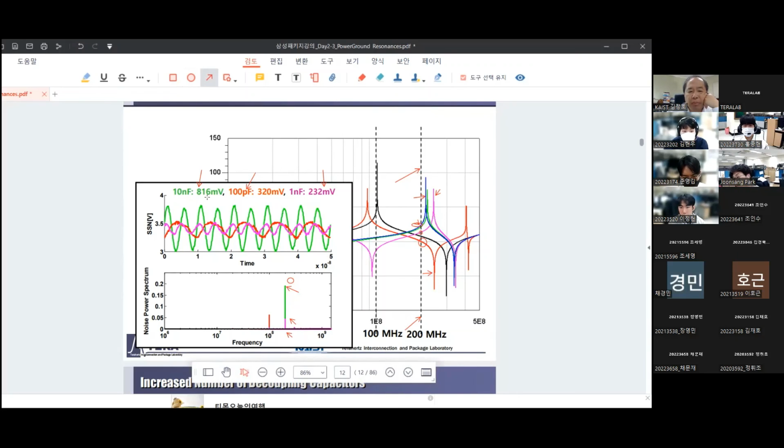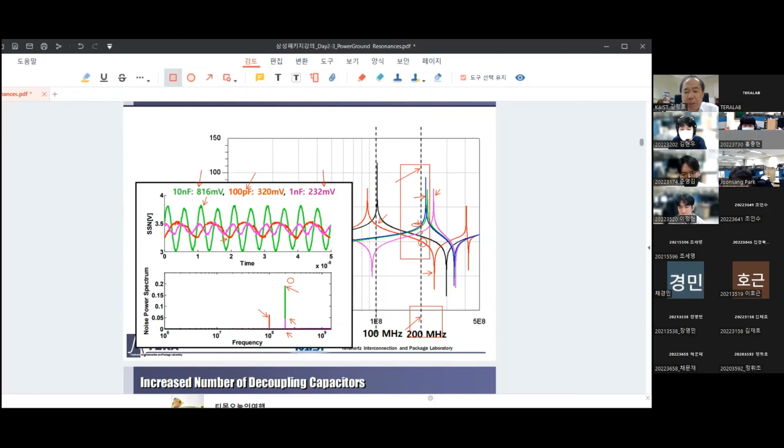Also in the time domain, the blue line has very high peaks with high frequency components. The red line, on the other hand, has higher impedance around 100 megahertz, so it has more 100 MHz peaks, and it has smaller size, but it changes more slowly. What I'm saying is, let's assume you have a certain current spectrum and impedance value. Exactly this impedance has correlation with the peaks.